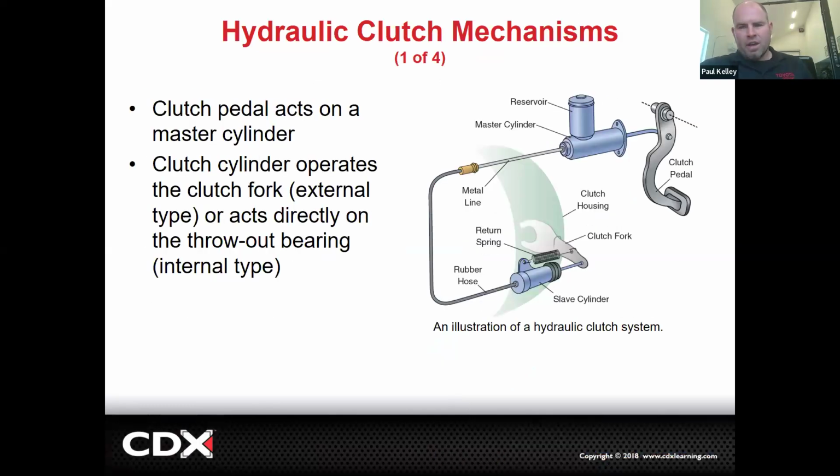Cool. Now that you've gotten mostly an understanding of the pedal and its adjustments, we'll apply this a little more specifically to hydraulics. Your clutch pedal has a push rod, right? That's the one that needs to be adjusted. That's probably going to go through the firewall. And then the clutch master cylinder is generally outside. There are some with them inside. Those are kind of a hassle.